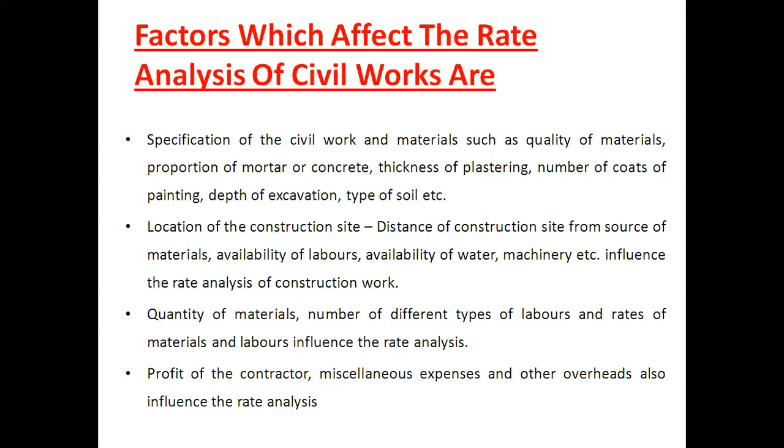Like centering contractors, they are just doing the work of centering only. Apart from that, they are not interested to do any work. Shuttering contractors, painting contractors, plastering contractors. So these are specified works, and they are specialized persons who are dealing with them. So the number of different types of labors as well as their categories will influence the rate analysis. Then profit of the contractor, miscellaneous expenses and other overhead charges also influence the rate analysis.